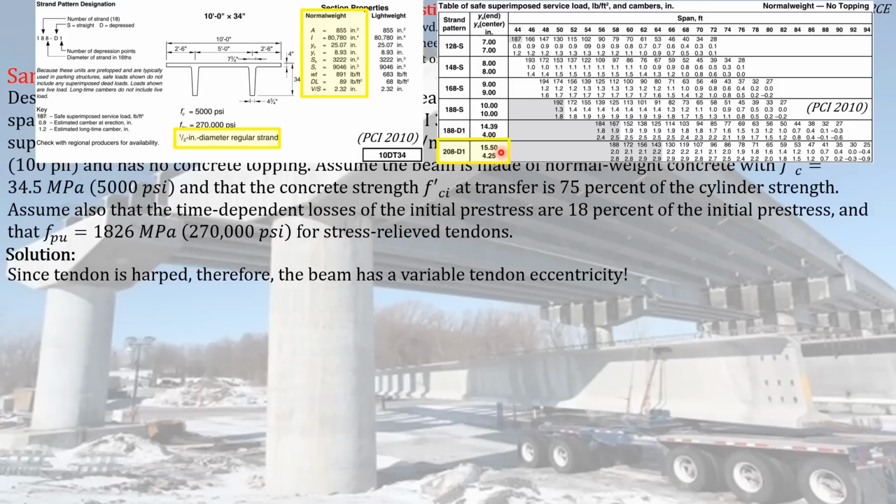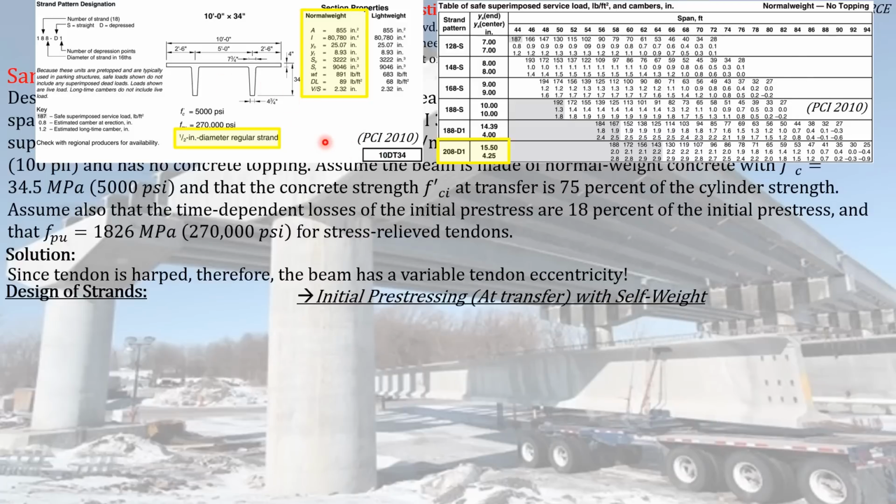So since we now have a section that we know will satisfy the given demands on the problem, specifically the loads, we can now design the strands that we have to use for this particular section. So again, for the design of the strands, we will use the stresses that will be induced in the concrete element at the initial pre-stressing and transfer with self-weight.